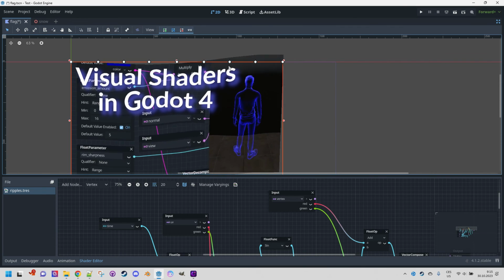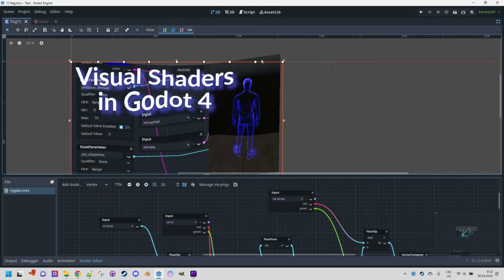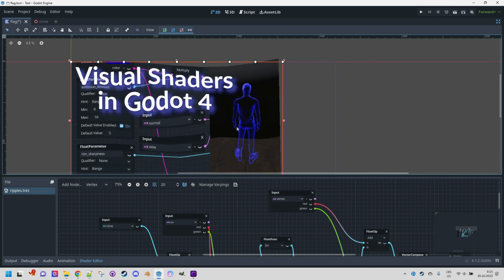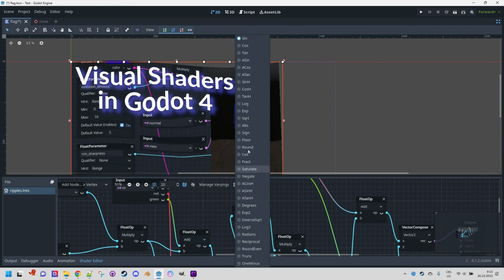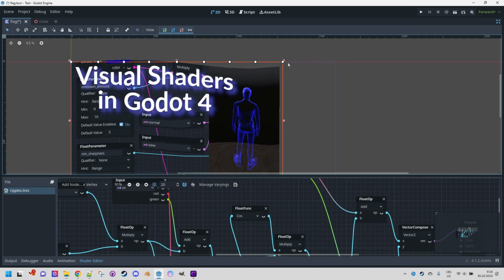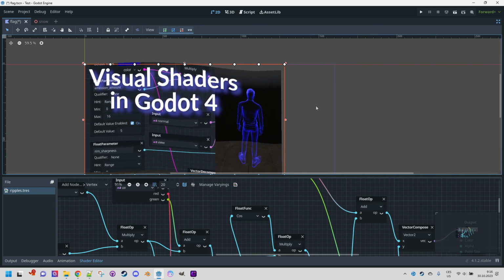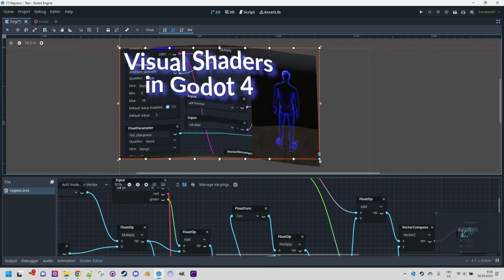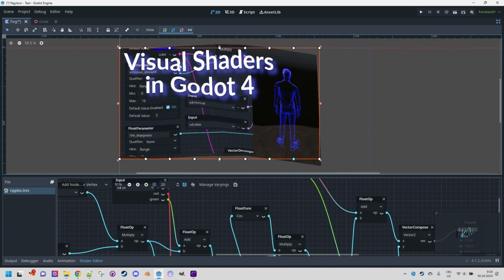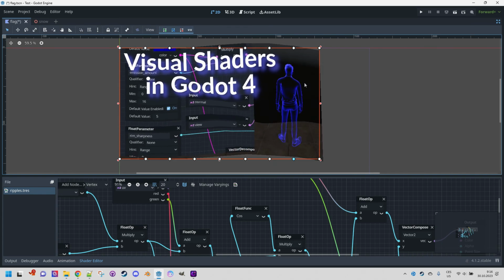By the way, we can see that the corners of the flag appear to be circling, which looks a bit unnatural. So we'll improve their movement by shifting the phase and changing the sine to cosine for the x coordinate. Let's find it, it's here, sine to cosine. Okay, that's better. Of course, you can add vertices on the vertical side as well to create a denser mesh to make the flag waving smoother. It depends on the specific use case. However, the principle remains the same.